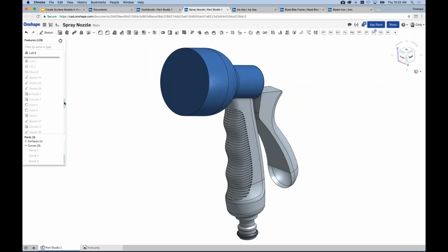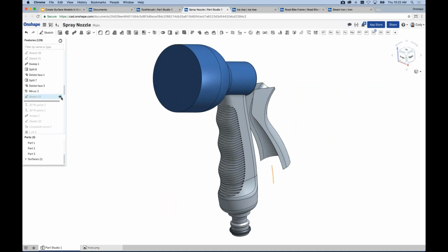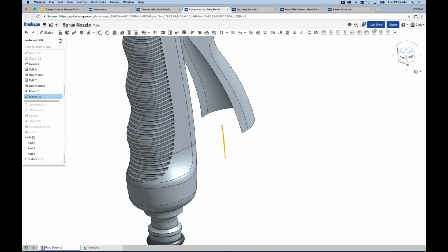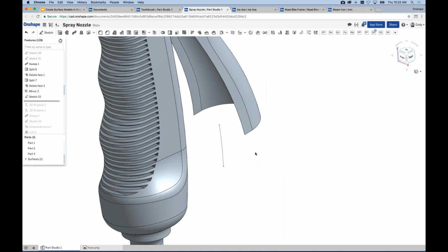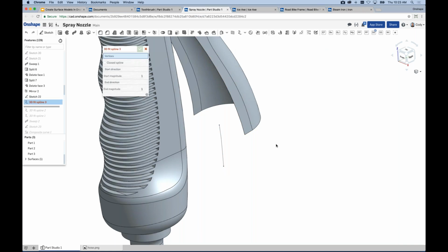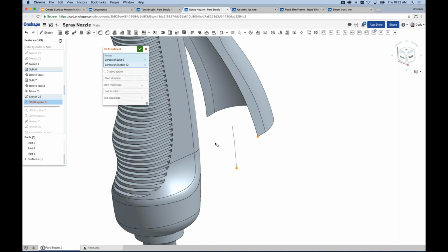Let's jump back into that spray nozzle, and roll back to this point in our design. I just want to show this simple sketch. What I want to create, that rounded bottom of the shape, is a 3D spline that passes through these 3 points, right? So through the 2 points of the handle, and this point that I've established is the very bottom of the handle. The important thing, however, isn't just that I get a 3D spline, but that spline is a smooth transition from these edges. So I can select 3D Fit Spline under that same helix dropdown, choose my points, point, point, point.